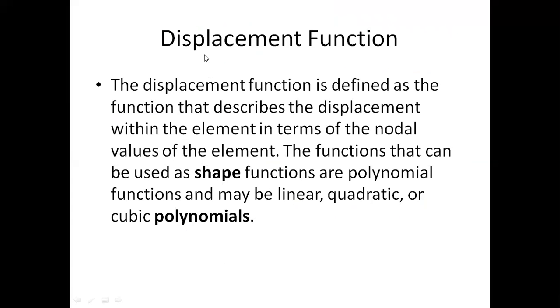These are the 1D element, this is 2D, this is the 3D elements. Okay, what is meant by displacement function? Displacement function is defined as a function that describes the displacement within the element in terms of node values of the element. Means displacement function is a part of the shape function, but it defines the relationship between force, stress and displacement of that part in the form of nodal displacement values or element displacement values. Okay, it is called a displacement function.